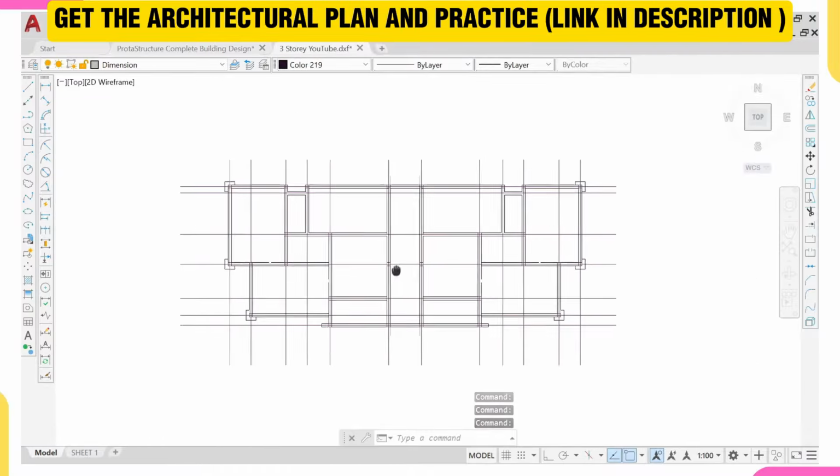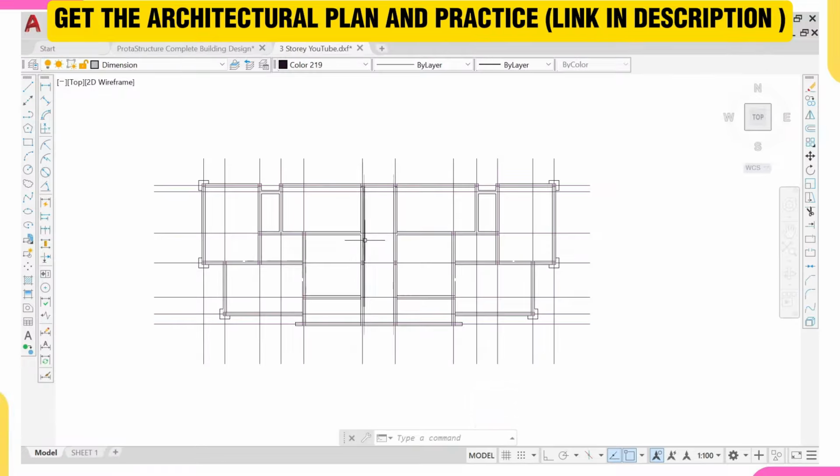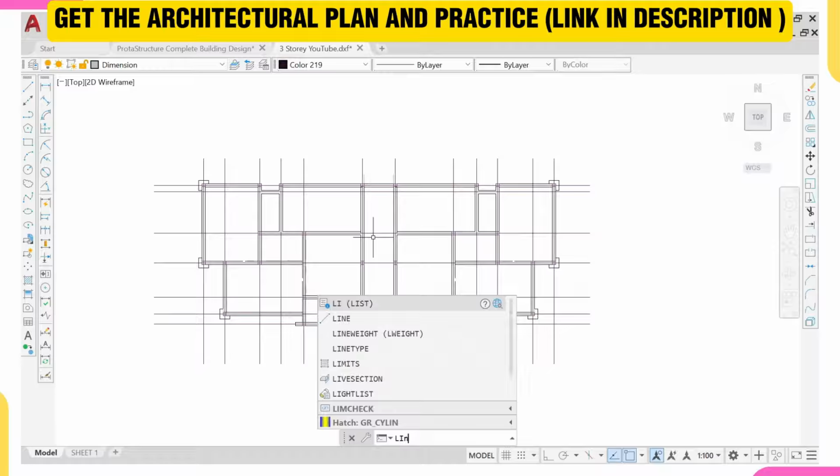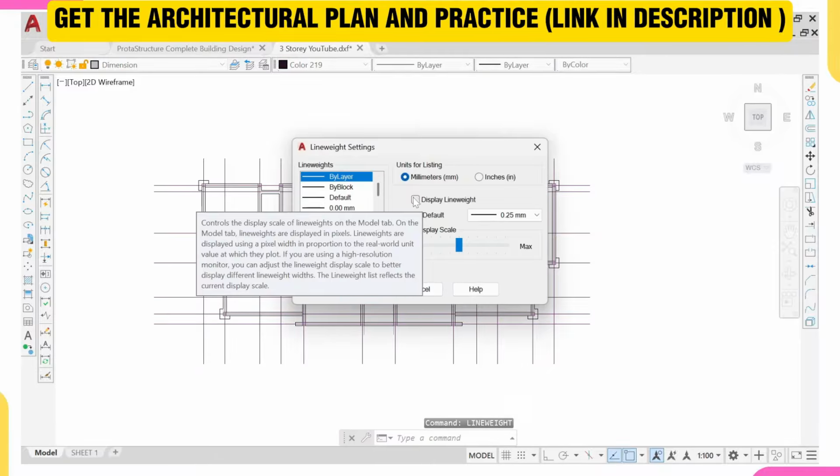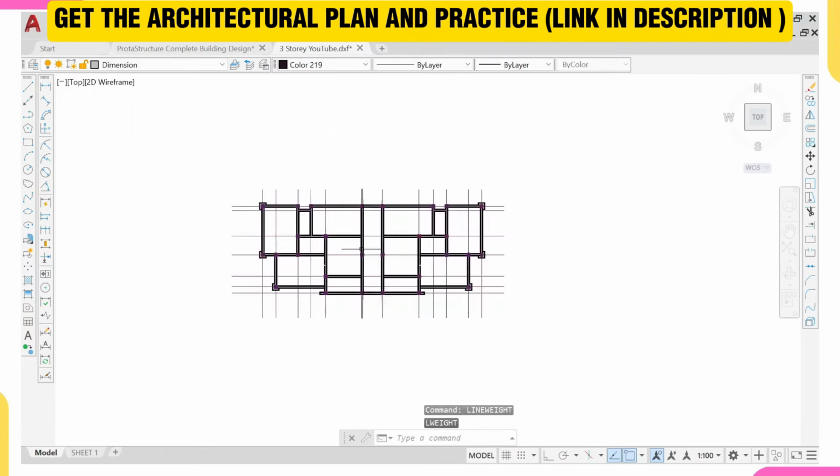But if you see it like this, don't panic. You just type line width. Yeah, this is line width. You now come to this point and click on display line width. Once you click on it, then click on OK. Yeah, you start seeing your line width.